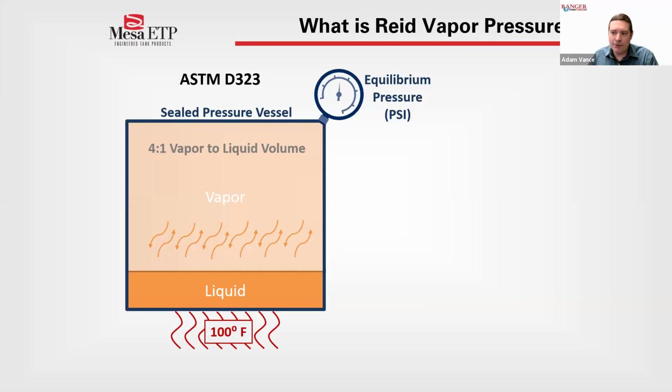So in the above ground storage tank industry, we hear a lot about vapor pressure, but what does that really mean? True vapor pressure and Reid vapor pressure are two values that tend to be closely monitored and discussed. We will focus on Reid vapor pressure, as this has typically a fixed value, whereas true vapor pressure is measured as a function of temperature and will change in different environments depending on the temperature that it's exposed to.